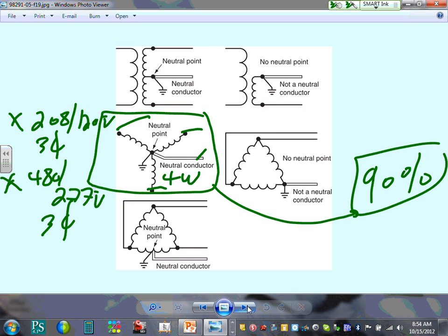That's a system that's going to create, you're going to start every building with a system like this. This is a generator or a transformer. Typically a transformer outside the building that's Y grounded, 4 wires, 3-phase and a neutral coming to your building, and from there you feed the whole building with either 208/120, which is the one that we are using, this one, or 480/277.